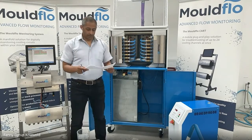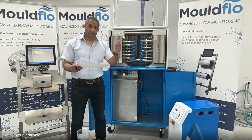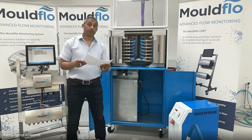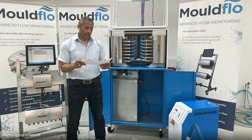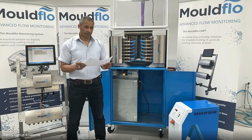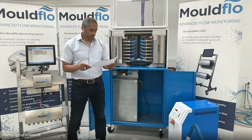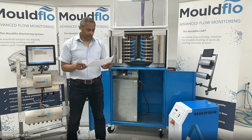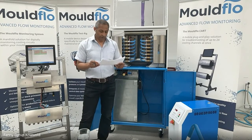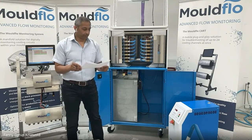We will go into more detail in the second webinar about the components and how they are installed on the machine. The purpose of the flow monitoring system is to monitor in real time the actual flow rate, temperature, and pressure conditions of the cooling channels. You can also set alarm limits for the desired flow and temperature of the cooling channels. With all these insights, you can troubleshoot to find the root causes of any alarms, and it's also possible to optimize the cooling time and cycle time.